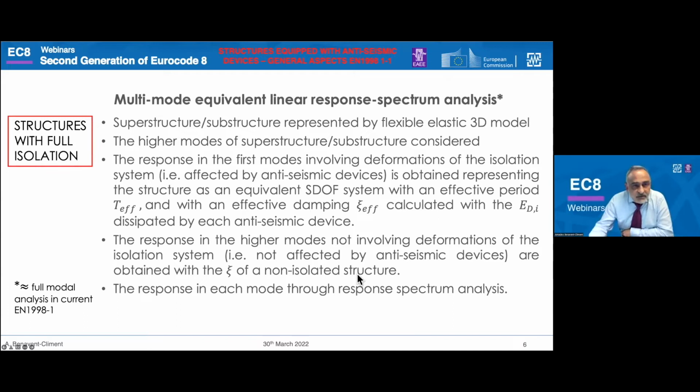The next method is the multi-mode equivalent linear response spectrum analysis that is also in the current Eurocode 8. It's what is called in the Eurocode 8 the full model analysis. In this case, the superstructure and the substructure are represented by flexible, elastic, three-dimensional models. In this case, of course, the higher modes are considered.